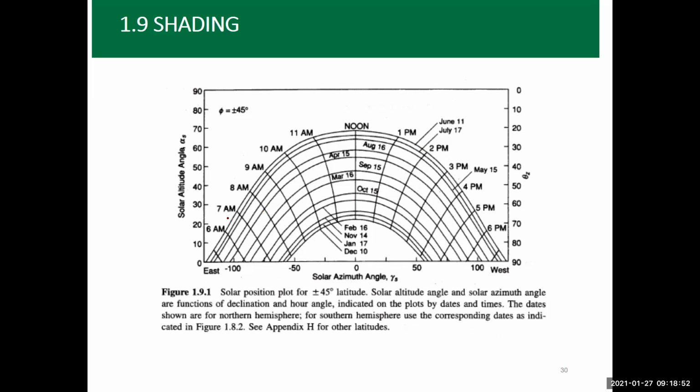And the hours of the day also are given values here. The window that we are interested in basically is this window. They call it the solar window, where basically the sun is more effective from 9 o'clock in the morning up to 3 o'clock in the afternoon. So this is the solar window where you are getting most of the radiation throughout the day. So whenever you have a figure like that, this is the location that you want to look for.